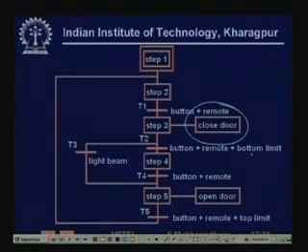On the other hand, if the limit switch is made, what will happen? The door will stop. So if either a button has been pressed or the bottom limit switch is reached, then immediately the door will stop. Or if the light beam is interrupted, then it will not only stop, it will actually reverse. So immediately it's going to reverse. If you have pressed a button to stop it and you press it again, then it will go to reverse. So we have captured the behavior of the garage door in this form using SFC.